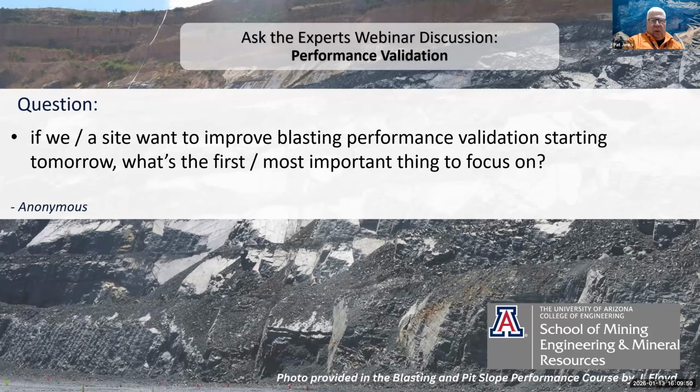So if I wanted to evaluate blasting performance to help with safety, one of the things I would pick on first would be to measure the catch bench width versus what the design intent was. And are we achieving our design acceptance criteria or that bench reliability? And if we're not, we need to make changes to protect that workforce.